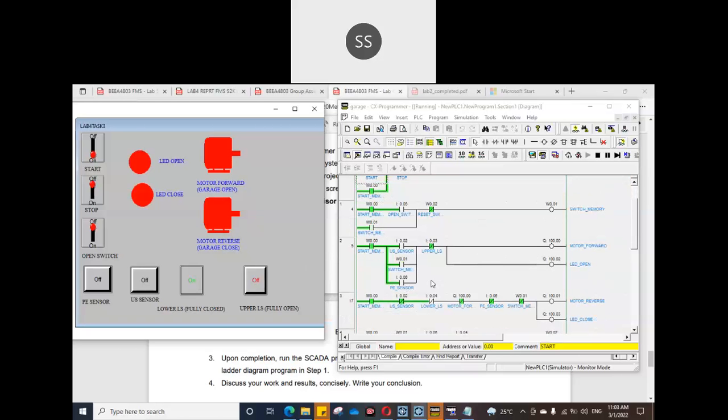We have set the upper limit as normally closed to protect the motor, because when the door is fully open, we don't want the motor to rotate again, which would cause the motor to spoil soon. So we have used the upper limit as a normally closed condition, and the same way for the lower limit.